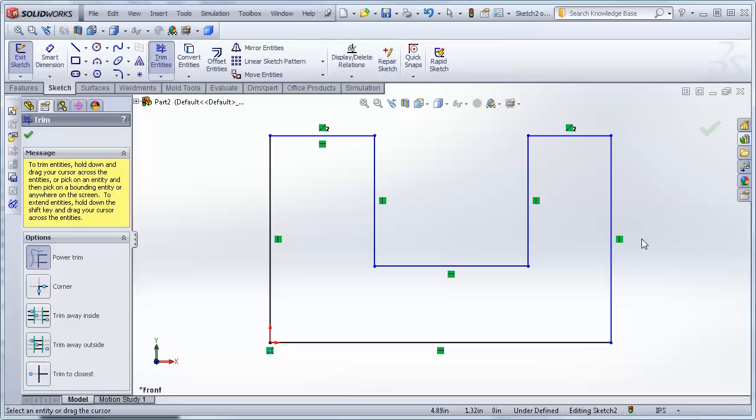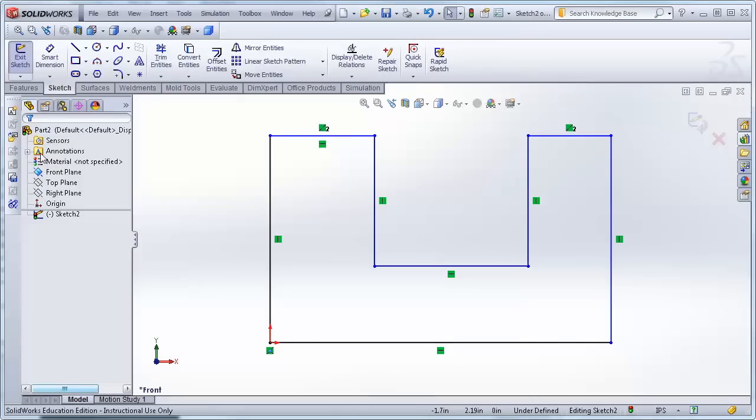And the question is, I've already built in some constraints which say that this line will be horizontal, this line will be vertical. These two lines will share this point, which is the origin of the coordinate system. So I've mostly got horizontal and vertical constraints, and some shared point constraints.